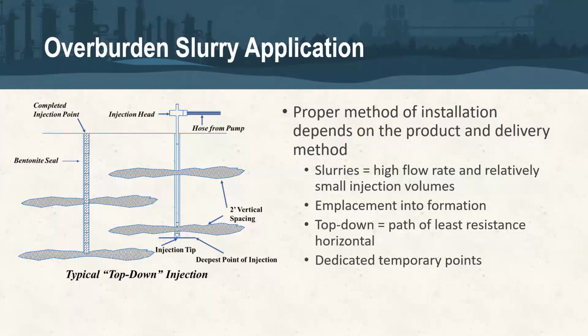And you can see there we offset each injection point to create that feature in the subsurface. So this is complete treatment, right? Whether this is injected in the phreatic or vadose zone, this is going to be just as good as doing in situ mixing, especially at depth where you're limited and have to move out of a zone that you could use yellow iron to do these installs.